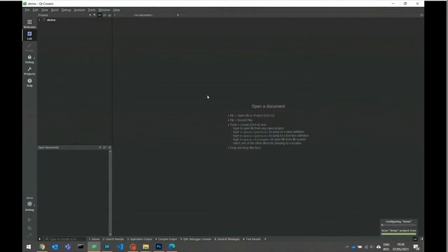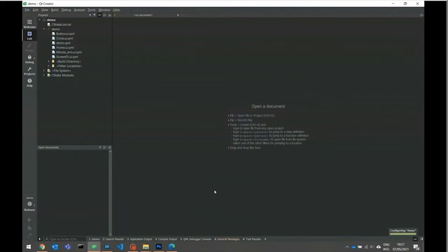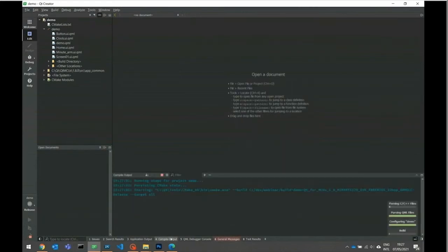Going to configure the project, pull all the dependencies, configure all the tool chains and the SDKs and so on. There's nothing you need to do. This is all included with Qt. Make sure you select the correct target here. And then same as for the demo earlier, just click run, it will build. It will also flash onto the board.